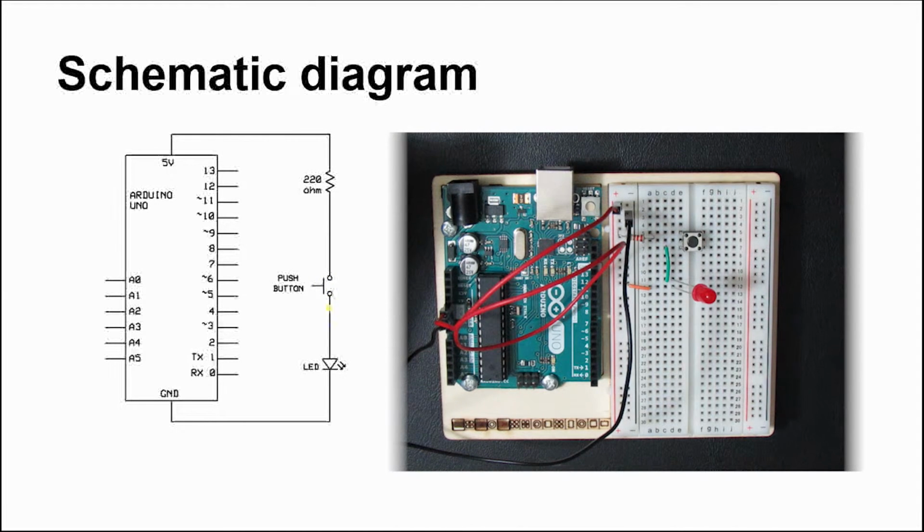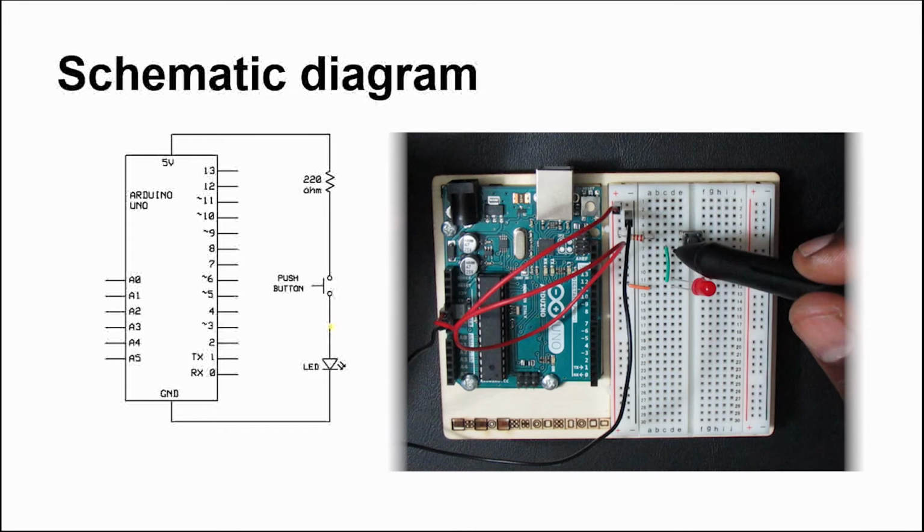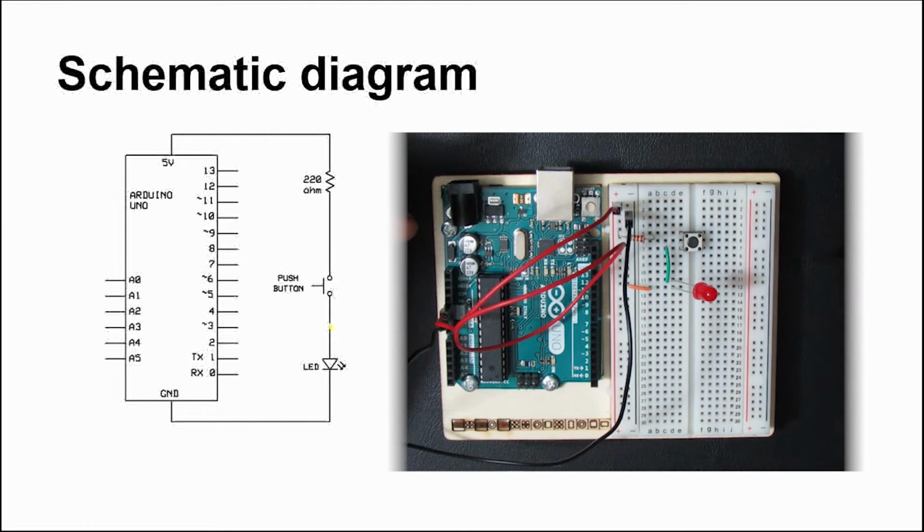After you come out of the push button, what's the next component? It's your LED. So we have this jumper here. Typically, we don't see jumpers in schematics, but the connection is still the same: it comes out of the switch, through this jumper to our LED. Okay, and in this case, on the schematic here, the anode side is represented by the bottom part of this triangle here, and this little flat bar here represents the cathode side.